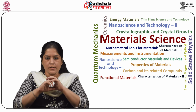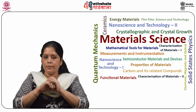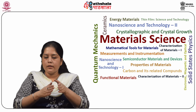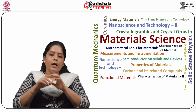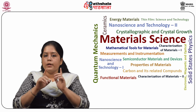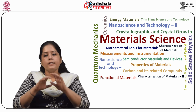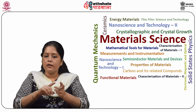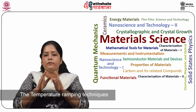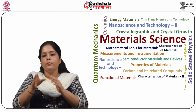Now, there are two types of this method. First is the pulsed periodic pulse technique. Here, the sample to be measured is subjected to periodic step-like heating. And here, the sample is heated by radiation only, but cools by both the radiation and the conduction. This method is extremely attractive when heating and cooling rates can be very large with respect to the temperature ramping techniques.